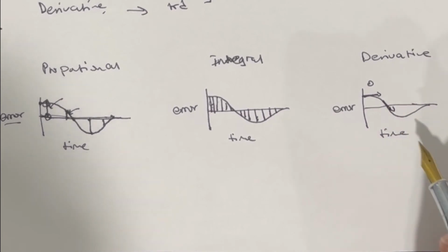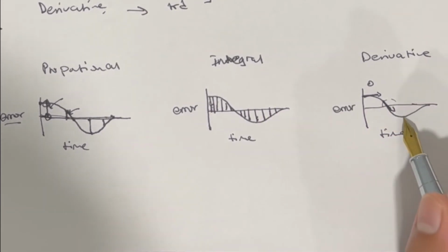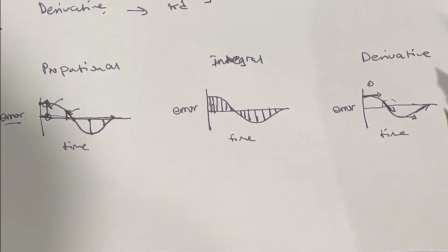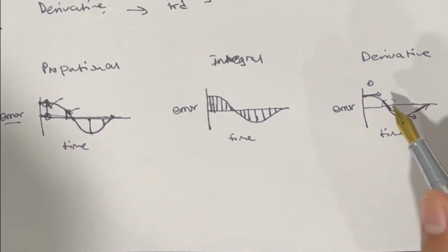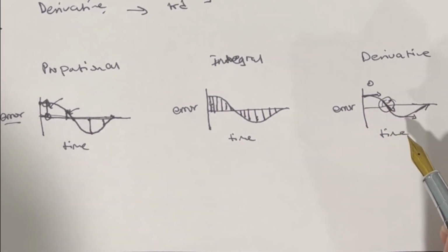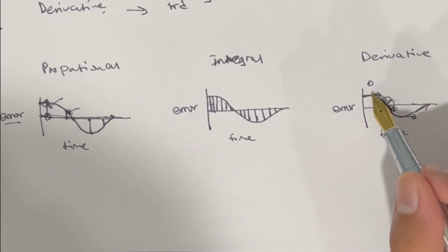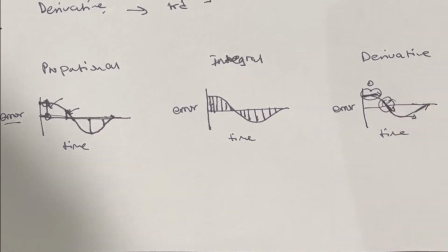This line that I've drawn here is steeper, so this would have a larger derivative. And here, again, it's a small derivative, and here it's become large. So what the derivative part of this does is it increases the speed change if it's seeing that it needs a large change in error in order to reach the center of the line. So over here, the derivative part would be larger, so the speed change would have a larger value here, whereas over here, the derivative is almost zero, so the speed change would be lower.